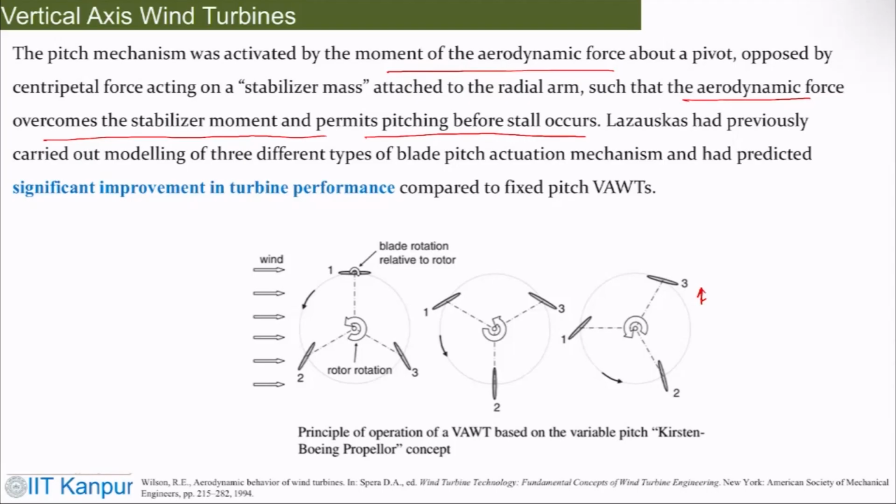In the continuous change, the flow is coming and hitting the airfoil like that. So there is a possibility of flow detachment, and when that happens, there could be stall. So by changing the effective angle of attack, the whole idea is that if this is your aerofoil and this is your angle of attack, which is exposed to the oncoming wind, there could be separation and stall. So you effectively change it so that the flow remains attached. Once you pass that point, you again change the angle of attack.